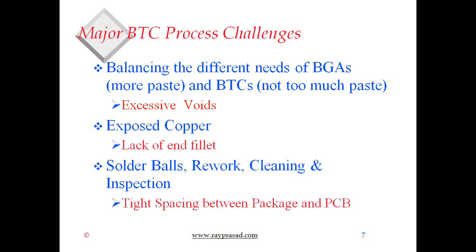That helps the BGAs. But in BTC, if you have too much paste, you run into the problem of floating, where the package starts to float. You also end up having a lot of voids. So that's an issue, and we'll see that in a few minutes.